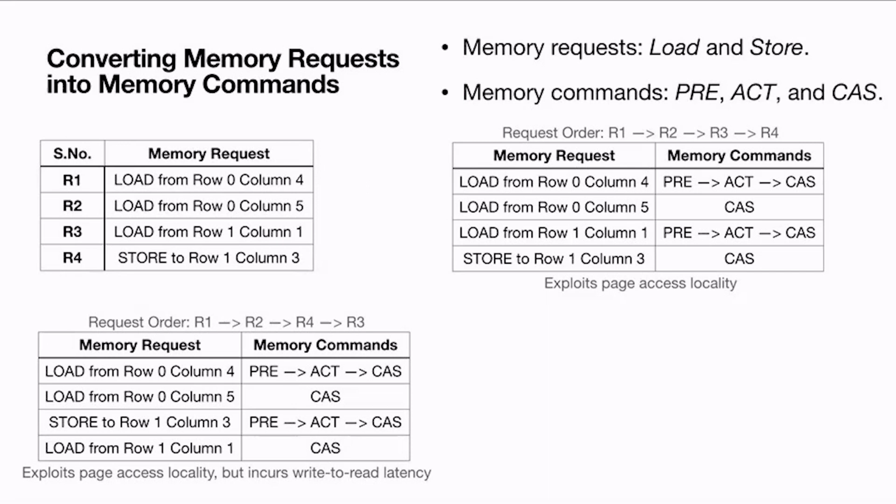And this latency is typically a few cycles, 2 to 4 cycles, and you have to wait for those many cycles so that your output circuitry settles, and then it is going to perform the read operation. But that is not there earlier, because the store is the last operation in the previous order, but here the store is the third operation. After that, there is a load operation.